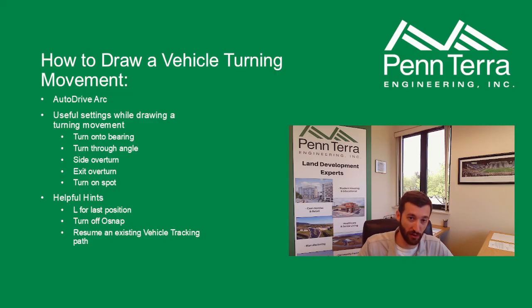We're going to talk about how to draw a turning movement. To do turning movements, the primary tool we use is called Auto Drive Arc. There's a few different tools within vehicle tracking that you can use. There's Auto Drive Arc, Auto Drive Bearings with a bunch of preset angles. What I've found is using Auto Drive Arc gives you the ability to apply the settings of any of those other ones. So I'd rather just use the same tool and tweak it if I have to, than have to remember what every single one of those tools does. So I use Auto Drive Arc.